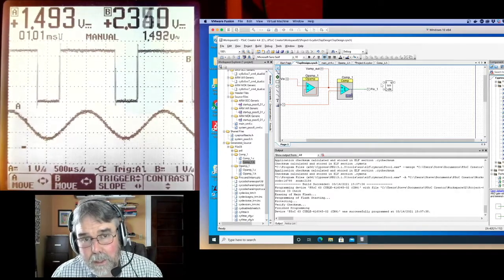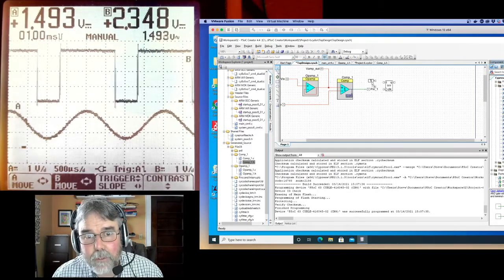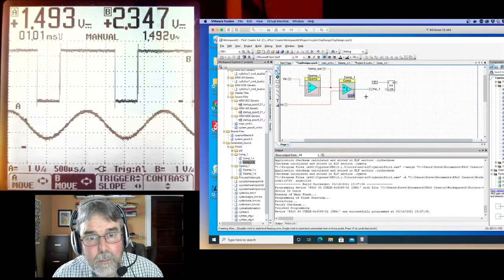So it toggles or doesn't toggle depending on whether the T input is high or not. For the first flip-flop, we take a logical 1, a logical high, so it always toggles, no matter what, whenever the clock goes. So what I'm going to do is grab here.